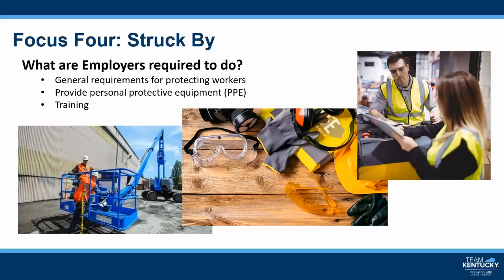All powder-actuated tools should be tested daily before use, and all defects discovered before or during use should be corrected. Powder-actuated tools shouldn't be loaded until immediately before use, and loaded tools should not be left unattended. Compressed air that's used for cleaning purposes has to be reduced to less than 30 pounds per square inch, or PSI, and provide effective chip guarding and PPE. All materials that are stored in tiers need to be secured to prevent sliding, falling, or collapsing. Employers must also ensure that toe boards are erected along the edge of overhead walking and working surfaces.